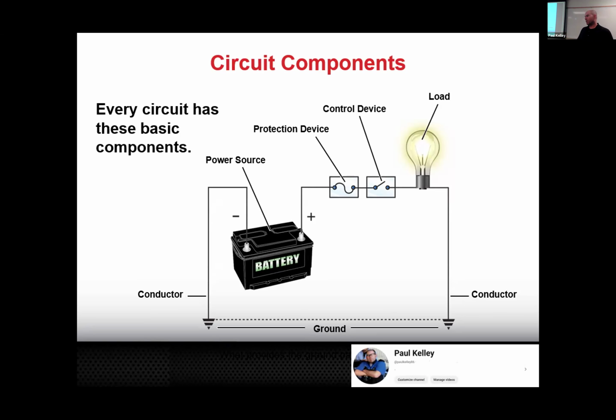They probably won't use a wire that'll handle 10. They'll probably use a wire that'll handle 12. The engineers are going to build a little bit of a safety measure in, but they're not going to use a wire that's going to handle 17, because if they're using a wire that handles 17, they're spending more money. That's more weight. It's not really efficient to be profitable. So they're going to calculate how many amps, and they're going to go up to just the next size, but not all the way to the next size where you can throw a 15 amp fuse in there. If it's got a 10, it's a 10. That's it. The wire may be able to handle a 12, but it's not enough to handle a full 15 or a 20 or whatever. That's just the way they do it.